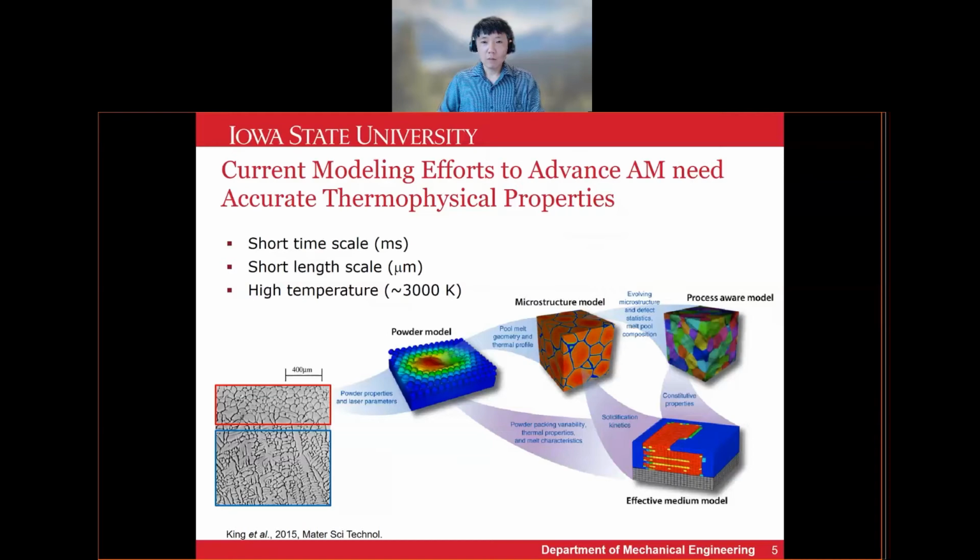In this process, the melt convection played a crucial role. Therefore, it is of critical importance to have a sound flow model to simulate melt and solidification, which requires accurate thermophysical properties. This is more important when you are developing new alloys for a specific in-space additive manufacturing process.